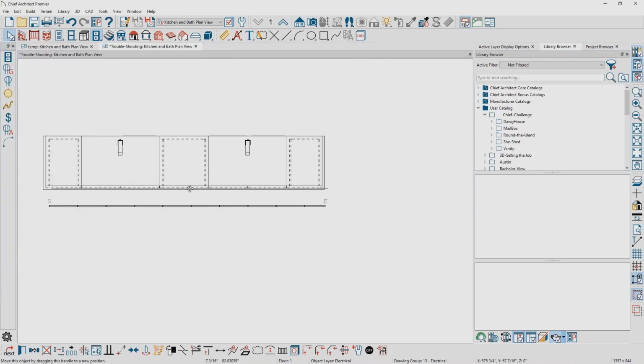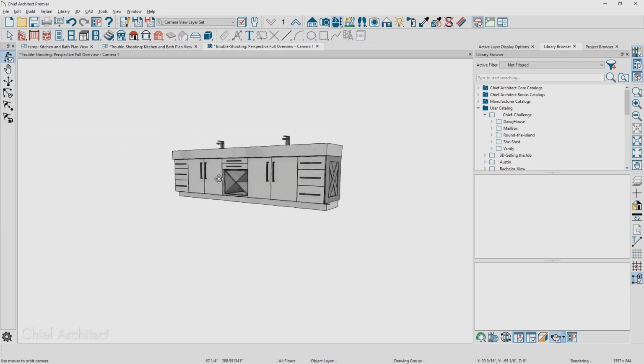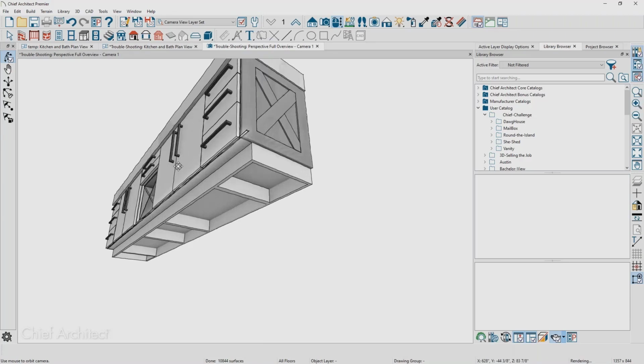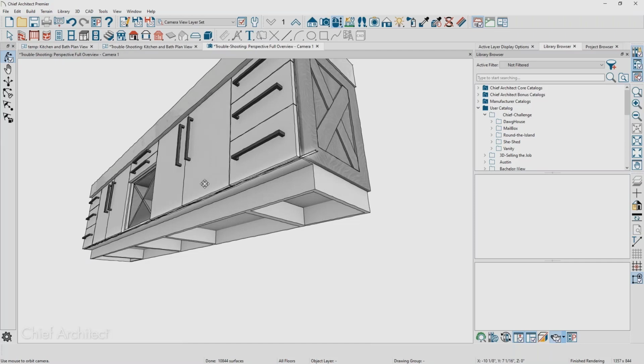And then as we slide that back into the cabinet area, of course, I don't have a room or anything. If we go back in and take a 3D overview of it, then you can control that once you have your room set up. The amount of light coming from those lumens, you can adjust it, and depending on the type of rendering you're doing, if you're doing the GPU ray tracing using the physically based rendering technique, adjust it, or if you're using the CPU ray trace rendering technique, you might have to tweak it slightly differently.